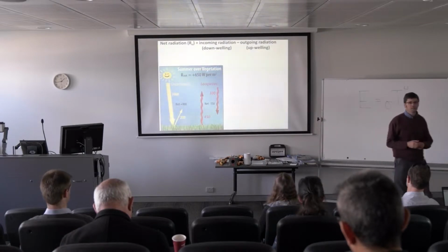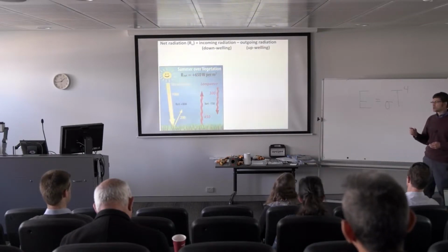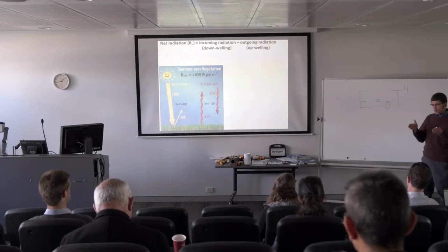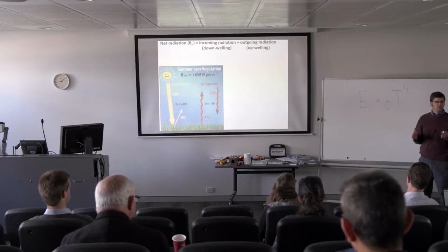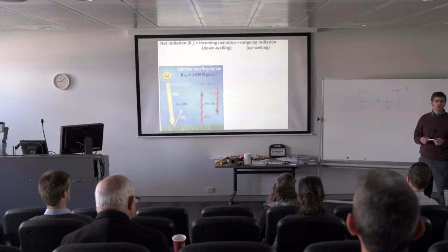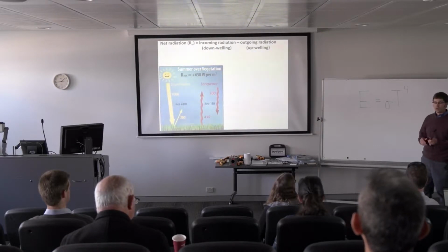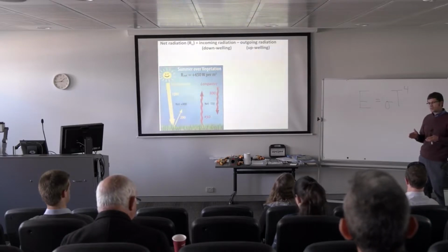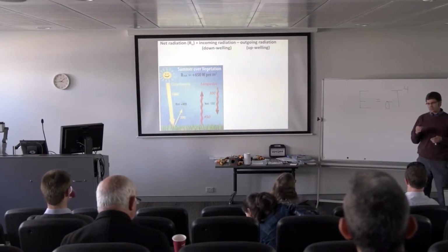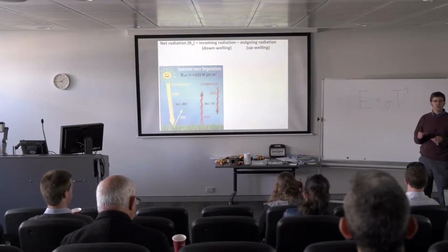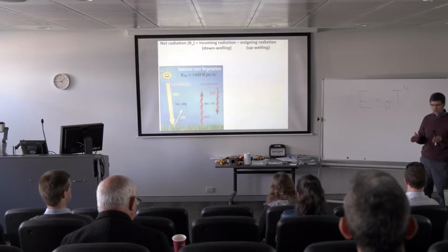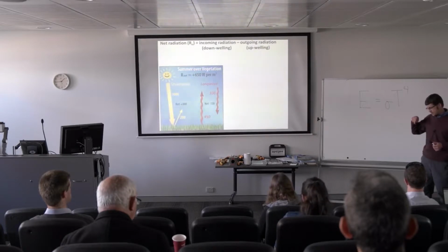The reason why is those infrared radiometers we were using outside, they're only measuring the wavelengths between 8 and 14 micron. You remember from the infrared presentation that I gave this morning, when we're trying to measure temperature, we have to have sensors that have a filter over them that only gives us 8 to 14 micron, because that's the atmospheric window where the sensor can effectively see through the atmosphere to the surface that we're trying to measure the temperature of.